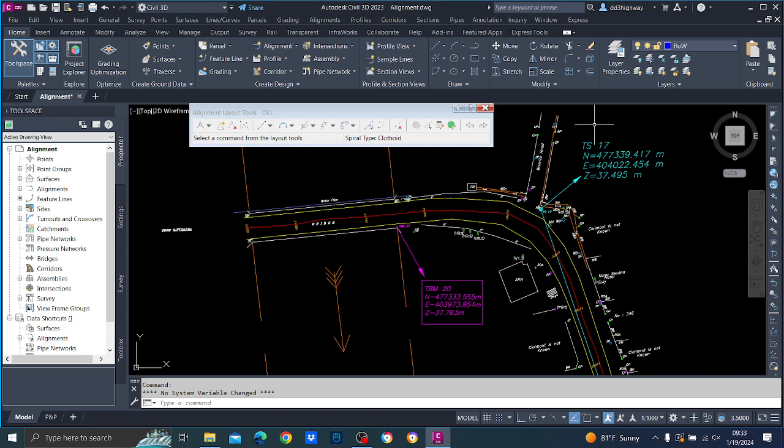Now we will try to design. First thing, in Civil 3D there is some basic theory. You have to start either from a fixed line or a fixed curve. Why? You are going to peg it somewhere. You have to peg the alignment, because after that you are going to change it here and there. But in some place you have to peg it. Otherwise you are going to design it in Colombo and it will end up in Delhi. So don't do that.